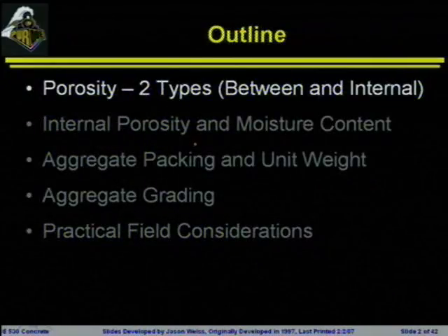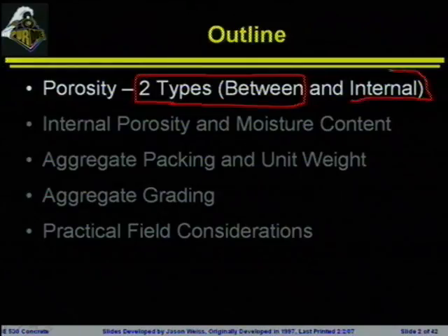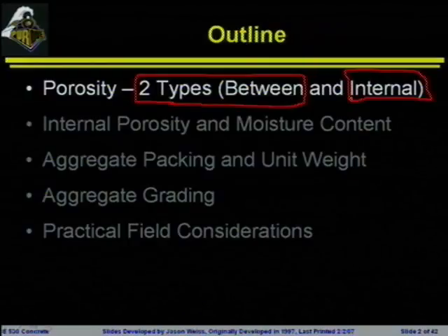So what I want to do is start off and talk about two types of porosity. These are the two types that are really of most interest. We have the porosity that exists between the aggregates themselves, and typically here we're looking at the space between the aggregates. And then internal porosity, which is the pores that are actually within the aggregate itself.